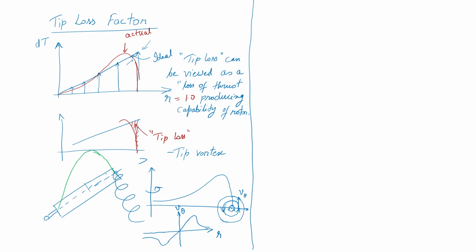Okay. Sometimes what happens is that larger rotors don't even have a single airfoil. So, they have two different airfoils also. So, the reason being that, for helicopter rotors, the bulk of thrust generation happens in the outboard section, ranging from say here to here. Okay. So, between say 65% to say 85%, that is the region where you will have the most thrust generation, because the moment you go to near tip, your tip vortex will influence.